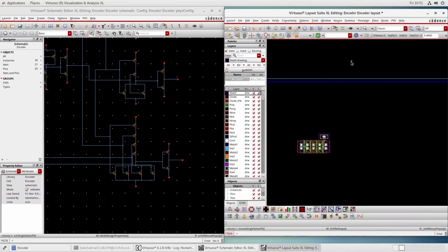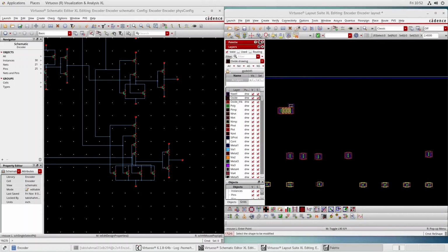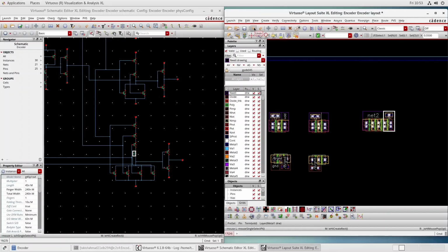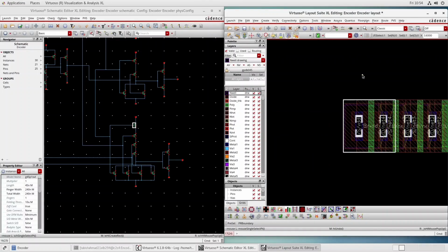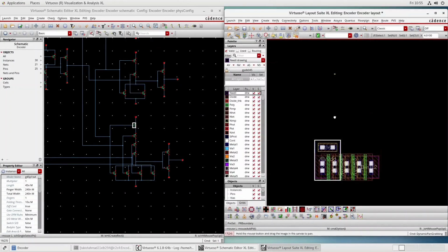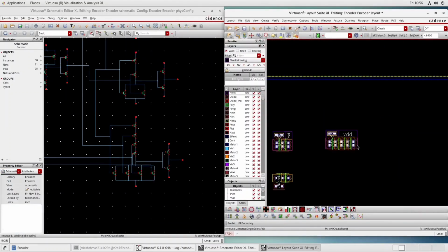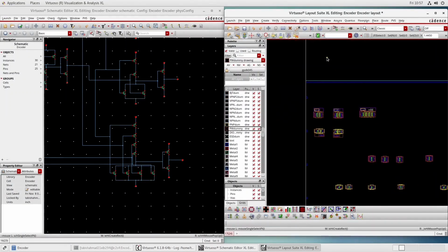You do not need to add this N-well and P-well for all the PMOS that are connected. You just need to place this well for the single PMOS and then use that rectangle tool to extend this to the complete structure.